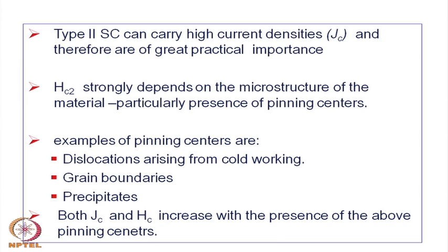Then you have another kind of defect in the crystal, particularly in polycrystalline material. It may not be there in the single crystal, but in polycrystalline material it will invariably be there. It is the junction or the boundary between two neighboring crystals, and that is a two dimensional boundary. So, these boundaries also act as pinning centers.